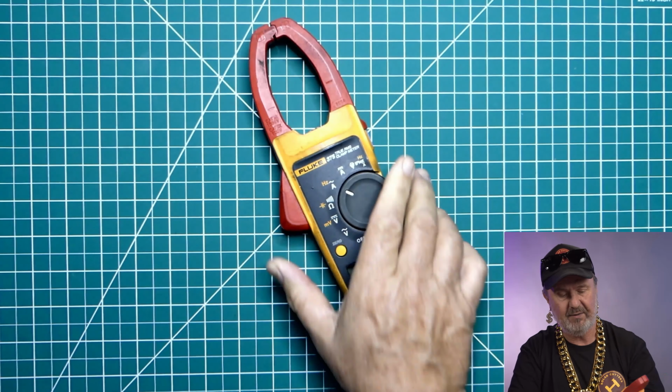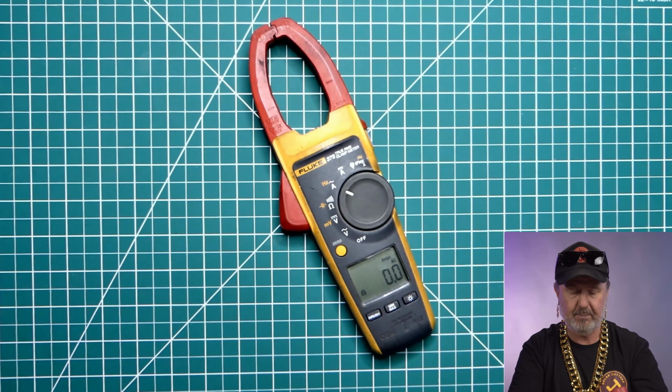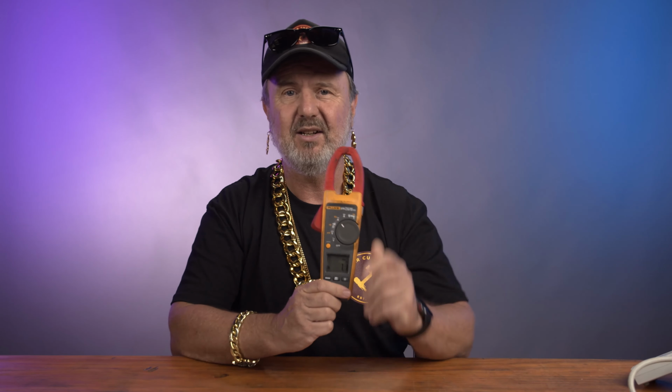So I can find out, well, volts as well, but I'm going to put it on amp range, and I put on AC amps because I'm measuring an AC appliance, but it can also measure inrush on DC if you need to. But for our purposes, we're concerned about mostly AC appliances in a home these days, and you're looking at the inrush on the active conductor. So that will be generally measured at the switchboard. So that's a peak that's really useful.